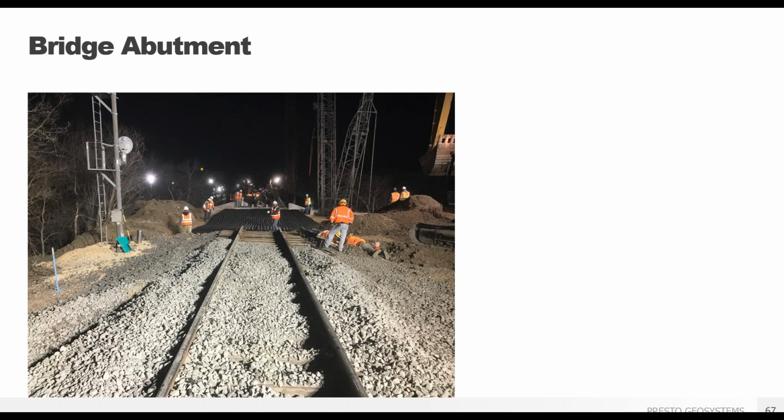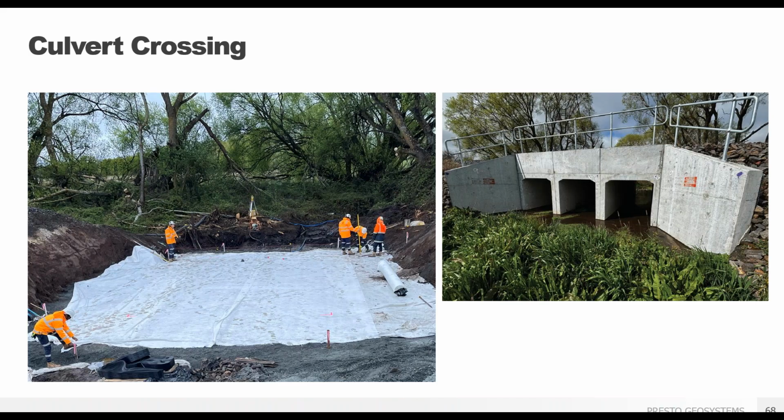We can't eliminate the consolidation settlement due to the weight, but we can almost completely eliminate any settlement due to the stress of the trains going over it. So we can almost completely eliminate any kind of differential settlement at a bridge abutment. So if you have any projects, reach out. We can give you some recommendations on bridge abutments.